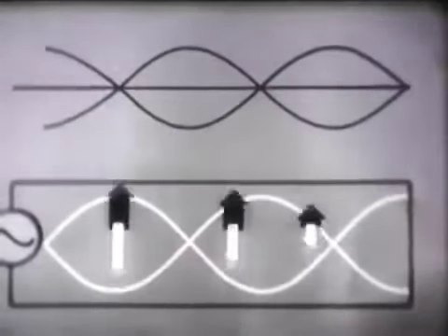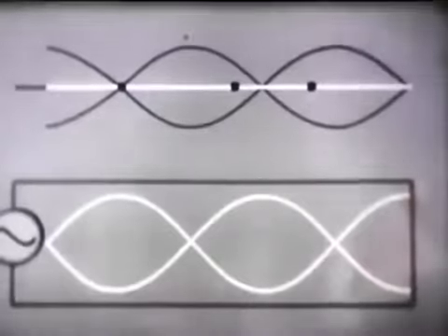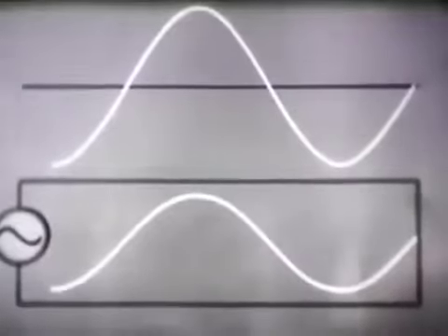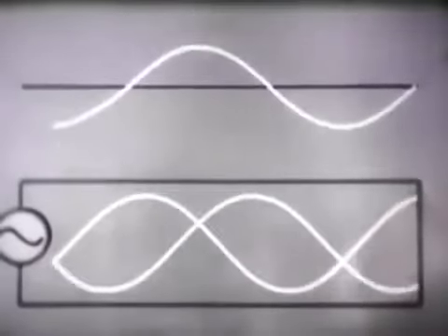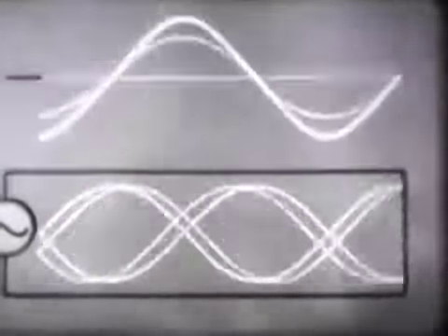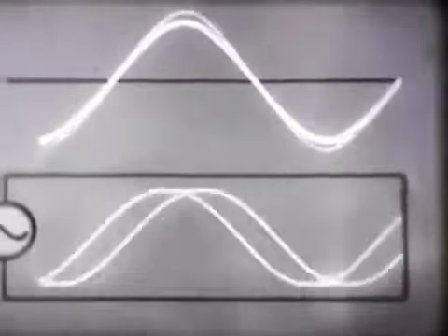Shifting our waves once again, our new measurements show that the positive and negative arrows cancel each other at all points along the waves, giving us a constant zero reading that follows the reference line. With 3 readings, we've gotten 3 sets of values for one standing wave. A measuring of all possible values of the standing wave will give us a picture of the varying values that exist between the constant zero points. The reading of the standing wave you will get with a current or voltage indicator is the effective value of these many curves. This value, of course, remains constant.